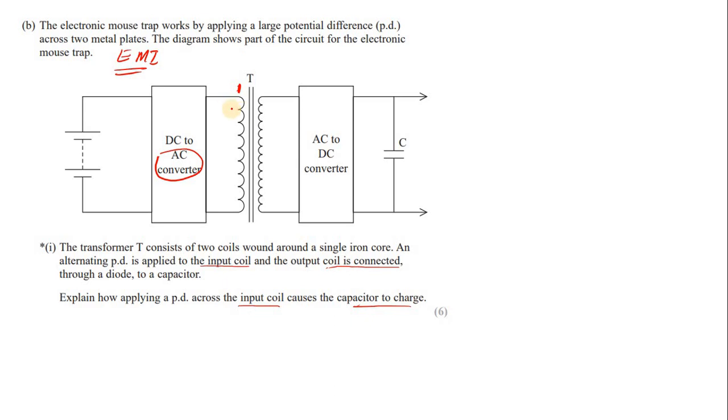This is not a correct diagram, but you can think of some shape of magnetic field, and this magnetic field is linked with coil number 2, and this magnetic field is alternating. So the alternating magnetic field links with the second coil, so the second coil's flux is changing.